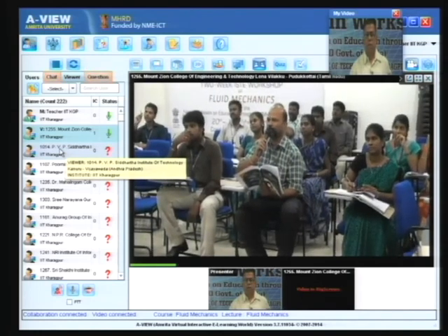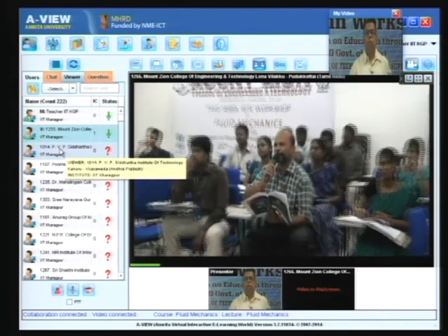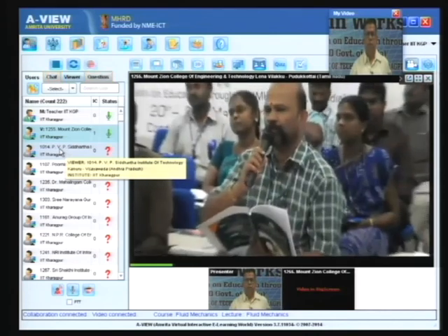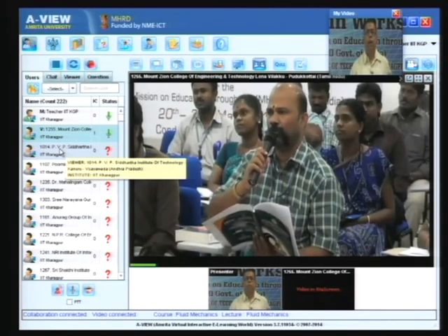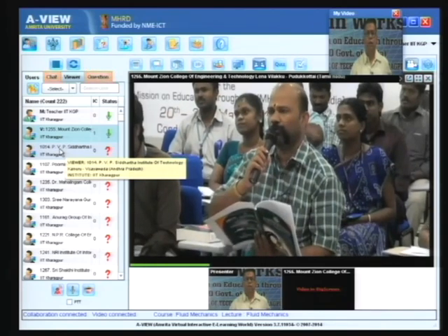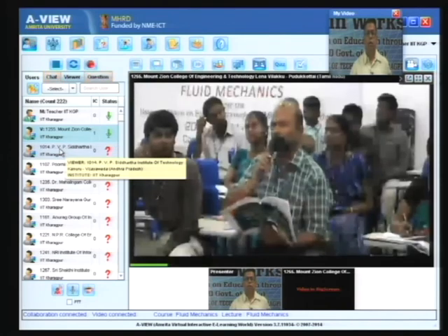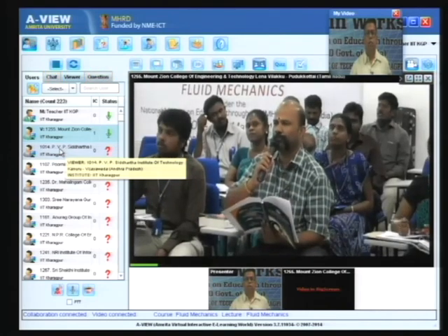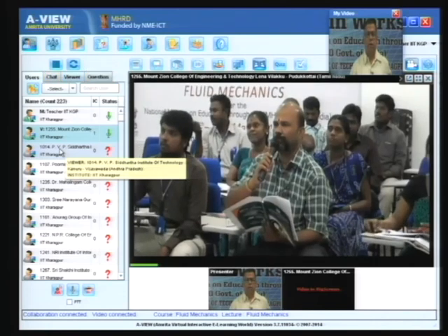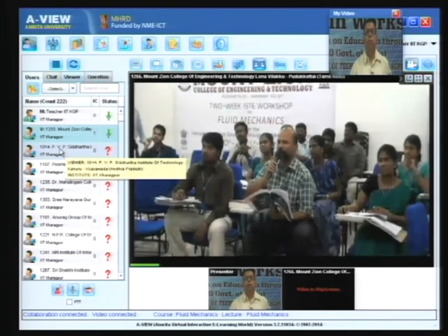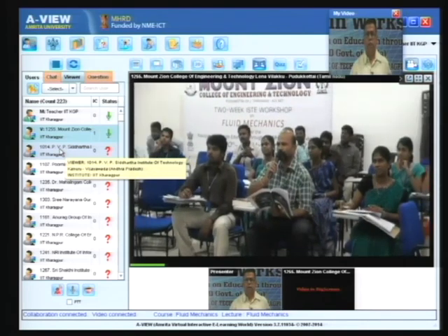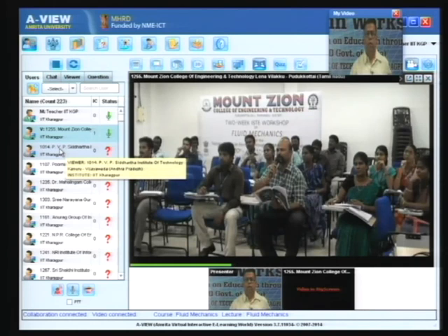Now, if your measurement is say 1 centimeter, then your error is 1 by 10, which is 10%. If your measurement is say 1 meter or say 50 centimeters, then it is 1 by 500. So, there is a big difference. Usually when you measure anything, you want the reading to be large, so that the relative error is small. That is why inclined manometers are preferred in some applications.